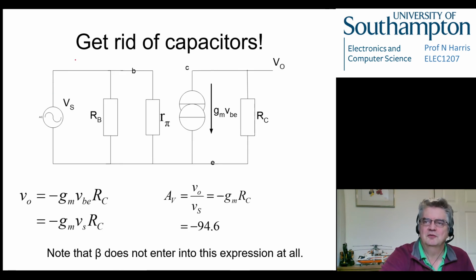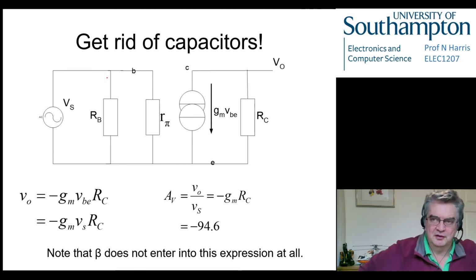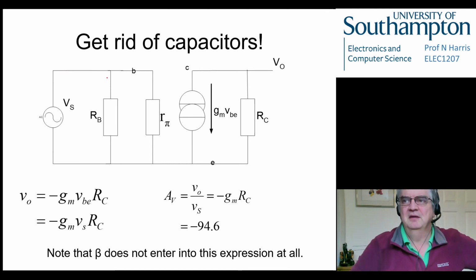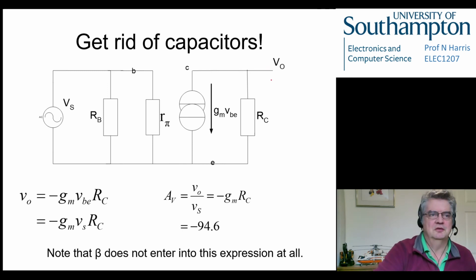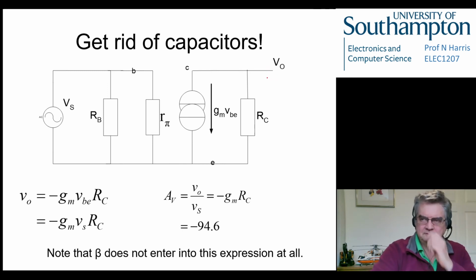So we've taken the capacitor that was here, and we've just said under AC conditions it looks like a short circuit, so under AC conditions we may as well not draw it, as long as we accept that this model only applies under AC conditions. And so the second capacitor that caused Mr. Shub so much trouble has now disappeared anyway, but only for the analysis. We haven't really got rid of it.